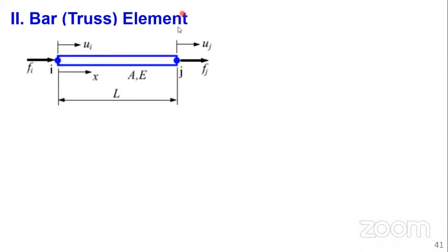So we have mentioned a few things, and we need to have some notation here, some definition. This blue outline is our truss element or bar element, and we said it carries axial load. So at the back of your mind, remember why we came with a spring element. The spring was like that. Then you say this is node 1, then you had another node 2. Then you talked of load application. Then you say this can only carry axial loading, compression or tension, so one degree of freedom. Same case with a bar element, it's a 1D